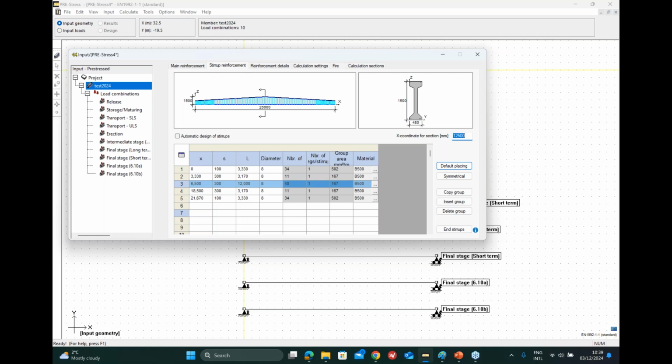So if you would have had 2-leg stirrups, let's say you have a distance of 100, and your shear distance is like 200, normally it will intersect, let's say 350, right, and we place it right in the middle, then it's three stirrups multiplied by 2 is 6, so 6 legs.